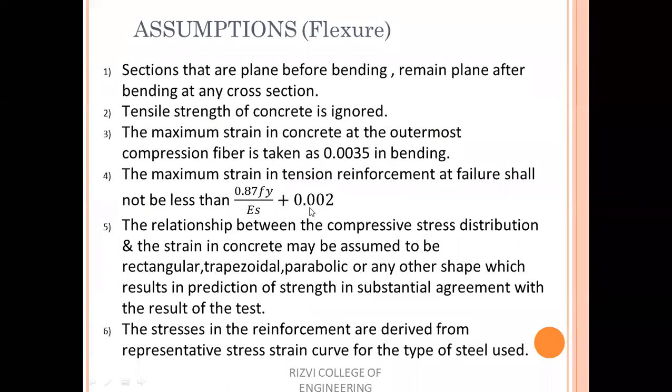The maximum strain in tension reinforcement shall not be less than 0.87 fy upon Es plus 0.002. So if you understand this, it does not become difficult to remember this. If you have that curve in your mind, you will easily understand this.